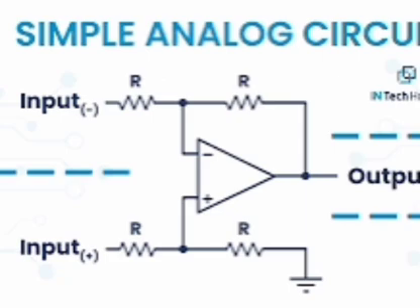CE amplifier with unbypassed RE: RI equals HIE plus 1 plus HFE into RE. If the bypass capacitor is disconnected, then AV decreases, and input and output impedance will increase.